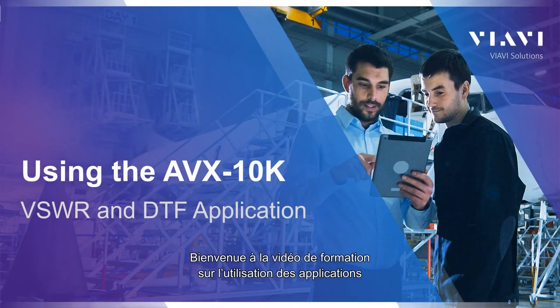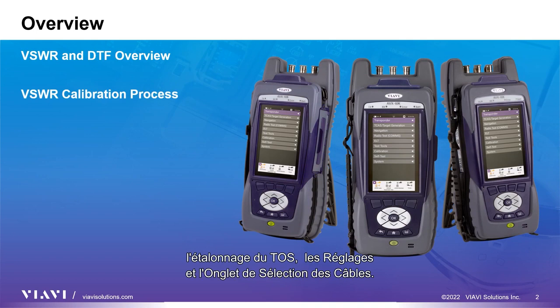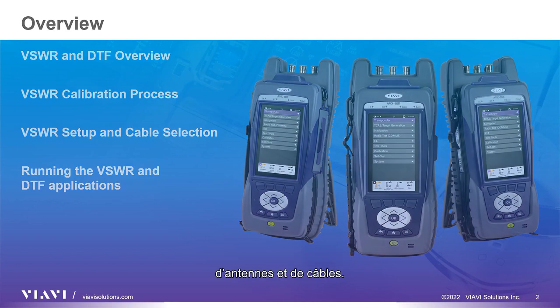Hello, and welcome to this training video on using the VSWR and DTF application on the Viavi AVX-10K test set. In this video, we will be discussing the basic concepts of VSWR and DTF, the VSWR calibration process, setup and the cable selection tab. We will review the provided cable settings and walk through adding a user-defined cable. We will then run through the procedures for testing an antenna and a cable.